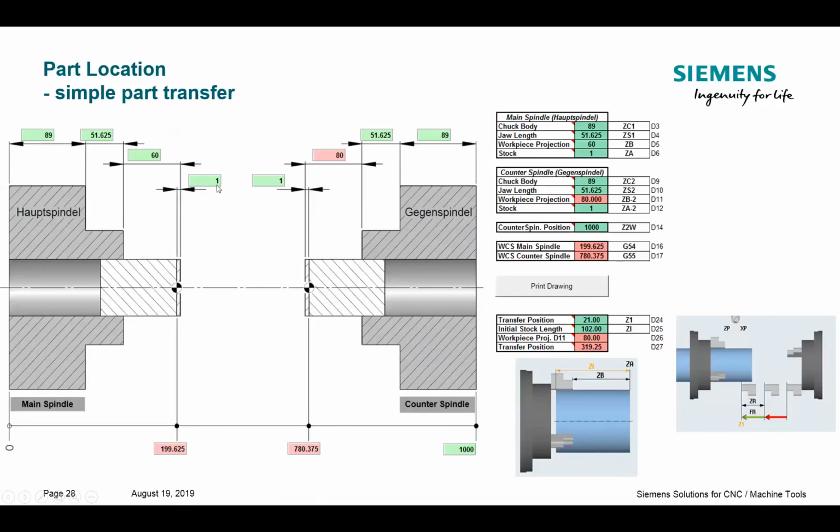In this case, I said I want to face off 1 mil. Maybe it's saw cut, it's rough, whatever. So I'm giving myself 1 mil. Initially, it's sticking out 60 mil, but once it's cleared off, the actual datum, or 0, is only 59 millimeters out. So just think about that when you come to your nesting.